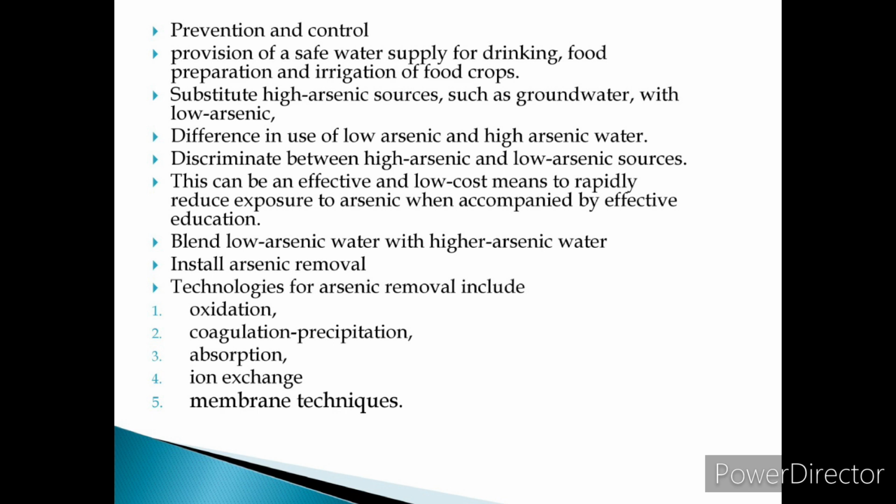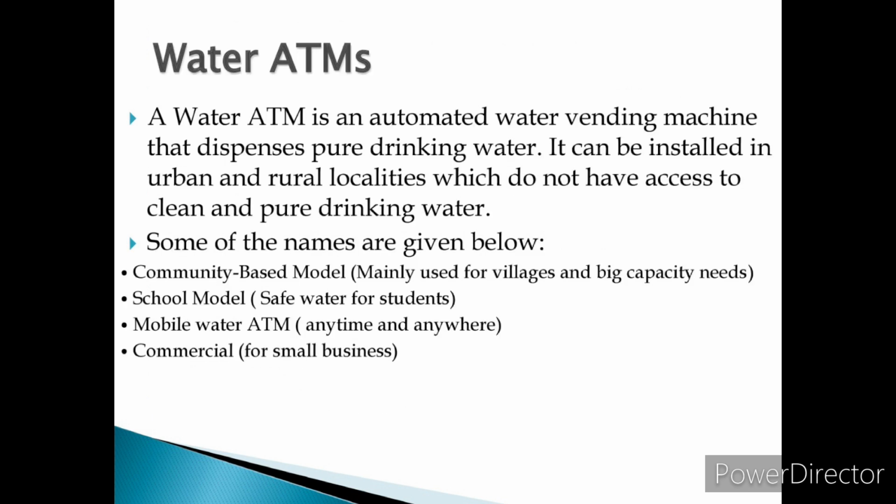We can also blend the low arsenic water with high arsenic water to achieve an acceptable arsenic concentration level. The technologies for arsenic removal include oxidation, coagulation, precipitation, absorption, ion exchange, and membrane techniques. The next is water ATMs. Water ATMs were introduced to make water accessible to everyone.